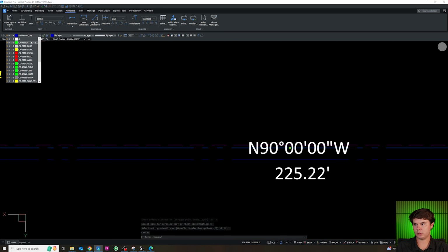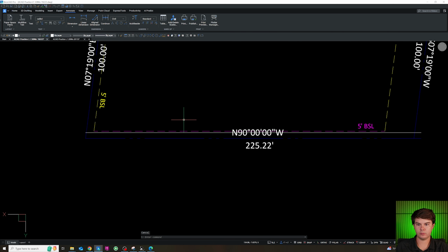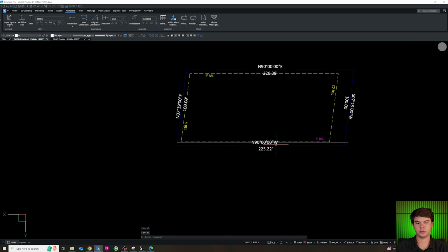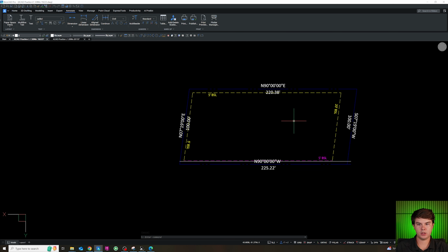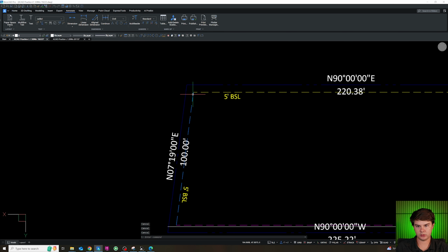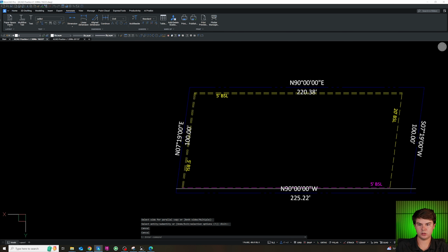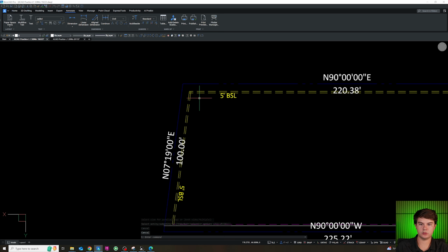So I'm just going to go ahead and offset that, make it 0. That way we know where our first constraint is. Now we'll start wireframing. I know that the building is going to be up in this corner. This is our secondary constraint. So I'm going to offset this 1 foot and 1 foot just to make sure our corner of building is not too close. Then I'll draw in our building.